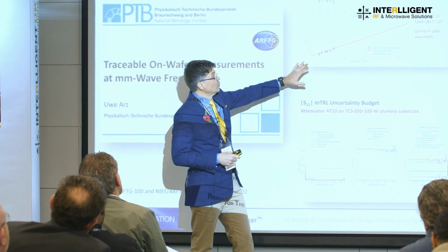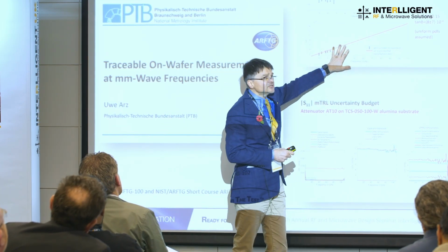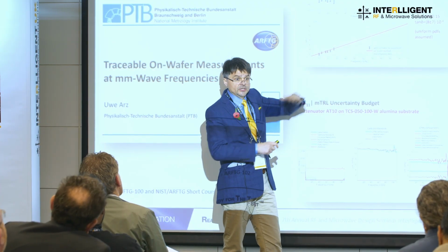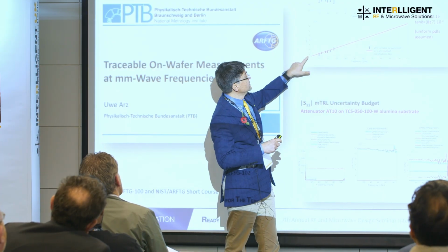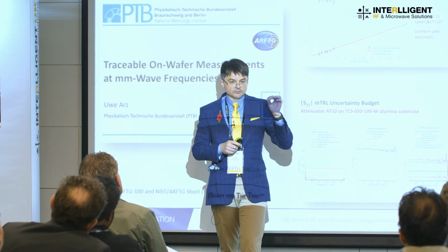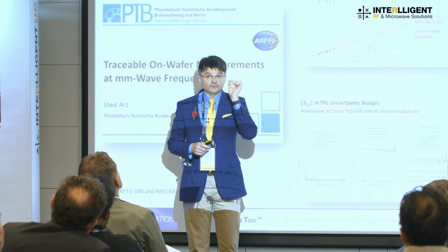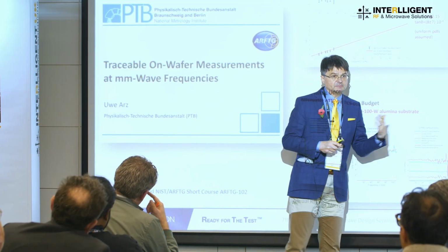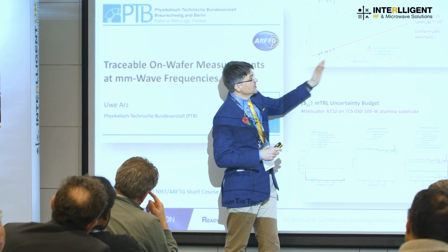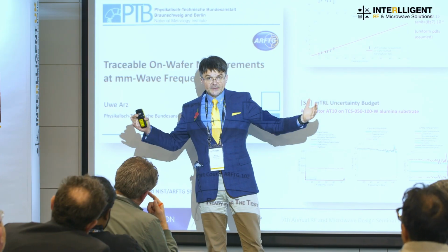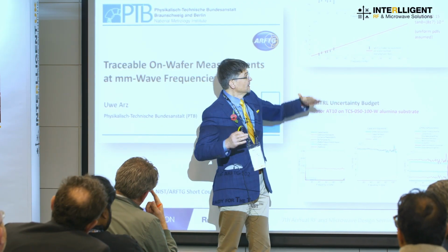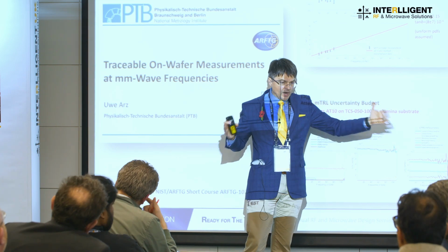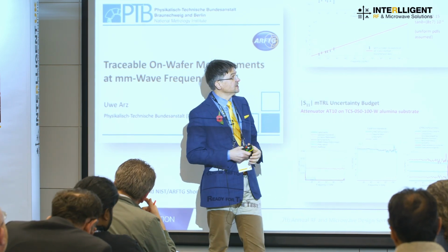Also understanding the dielectric constant characteristics in the broadband frequency range. Previously, metrologists were able to extract it only at a few frequency points, but there was work done at NIST and PTB as well on how to measure dielectric constant for the broadband in a relatively wide frequency range and correlate it with the standard methods.